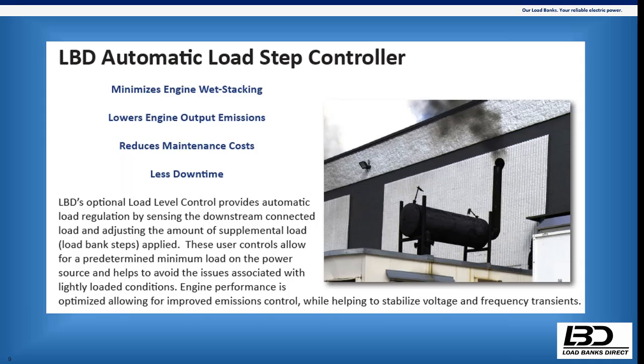And typically when we design these, it has to do with the capacity of the load bank as well, but it is also geared around what most people say: 30% is kind of the low end and 50% is kind of the high end for minimizing the wet stacking in these lightly loaded conditions. So we try and keep it in that window when we're supplementing load, depending on how heavily loaded the generator is. It varies a little bit, depending on capacity and a few other things.